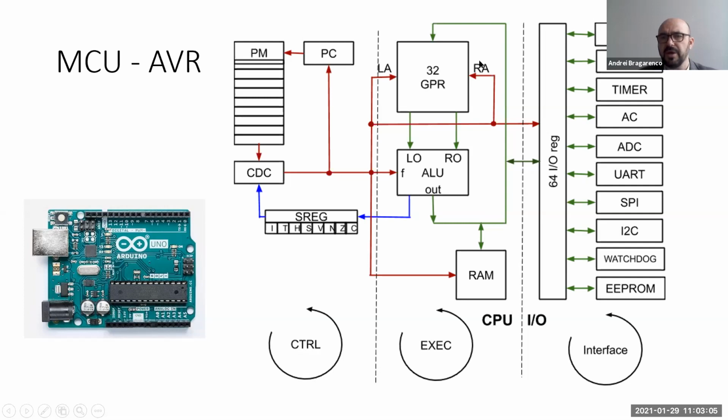state machine. We have another state machine, the execution state machine. This is executing arithmetical and logical instructions, meaning adding, subtracting, and so on. And the third is the transfer instruction, which is not related to any state machine. It is related just to transferring information, just configuring the data flow. So we have three kinds of instructions: control flow instructions, arithmetical and logical instructions, and transfer instructions.